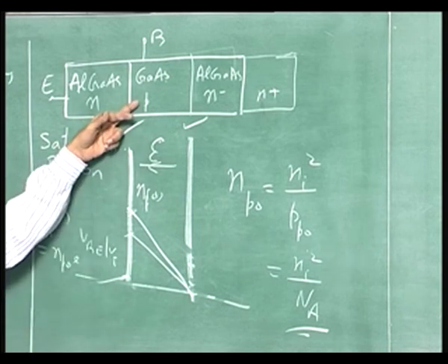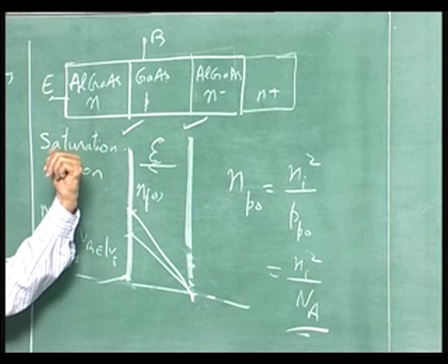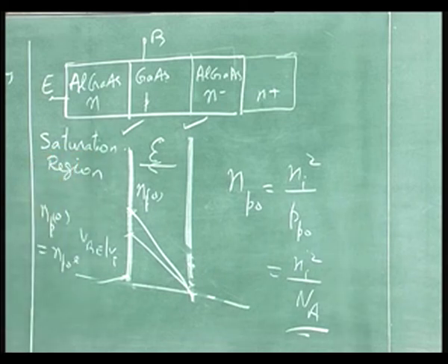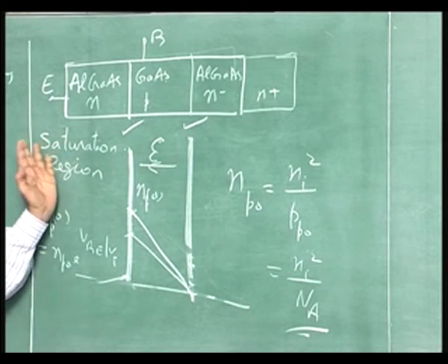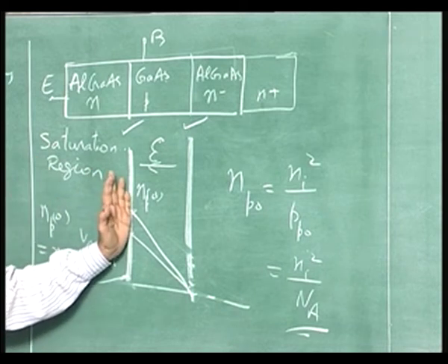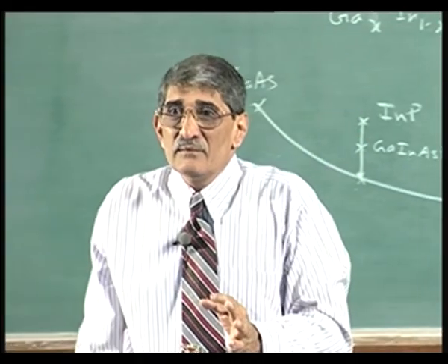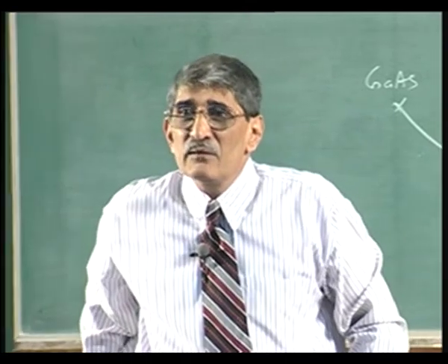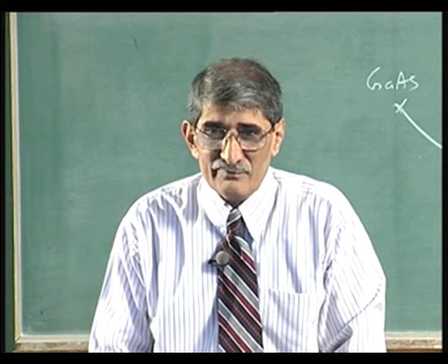dEg by dx. Band gap, if Eg is going on falling here, that is also in the same direction. Both are in this direction. Both the electric fields support the faster movement of electrons from emitter to the collector. So, this is the added benefit that you get for silicon germanium HBT compared to BJT with silicon alone. Okay.